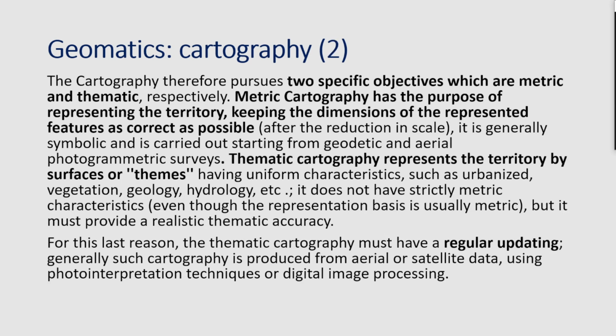Geomatics, Cartography, 2. The cartography therefore pursues two specific objectives, which are metric and thematic, respectively. Metric cartography has the purpose of representing the territory, keeping the dimensions of the represented features as correct as possible. After the reduction in scale, it is generally symbolic and is carried out starting from geodetic and aerial photogrammetric surveys.